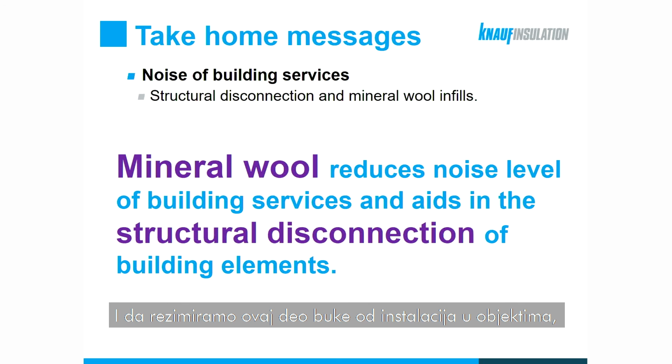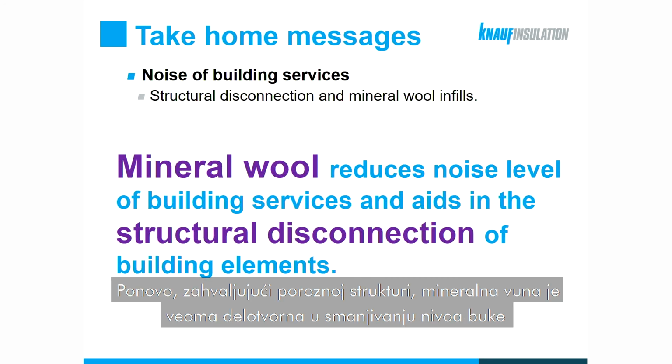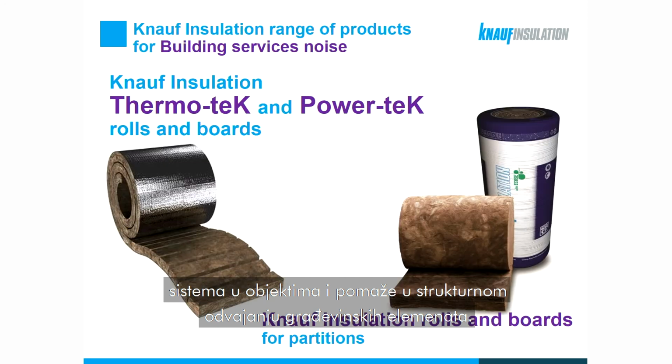So to summarize this part on the noise of building services, we have highlighted the importance of a structural disconnection and mineral wool infills. Owing to its porous structure, mineral wool is highly effective in reducing noise levels of building services, as well as aiding in the structural disconnection of building elements.